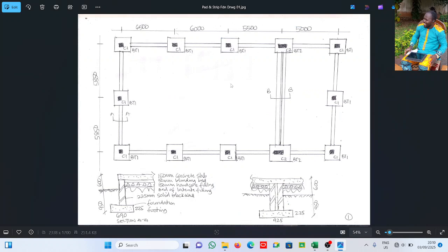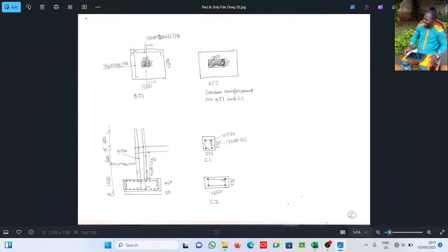You excavated and you put column base there. So where your base is, the sand there can no longer come back. You cut it away. Where your blinding is, this blinding. Before, blinding was not there. But now you have put blinding to displace the soil there. You need to cut that away. That's why they call it cut away.